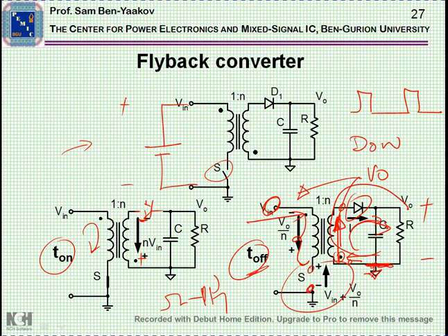Now, flyback transformers are used to, say, generate 5 volts, so if you start with 100 or 200 volts at the input, it'll be a step down. Now, in some cases, we would like to generate extremely high voltages, then N could be a very large number.